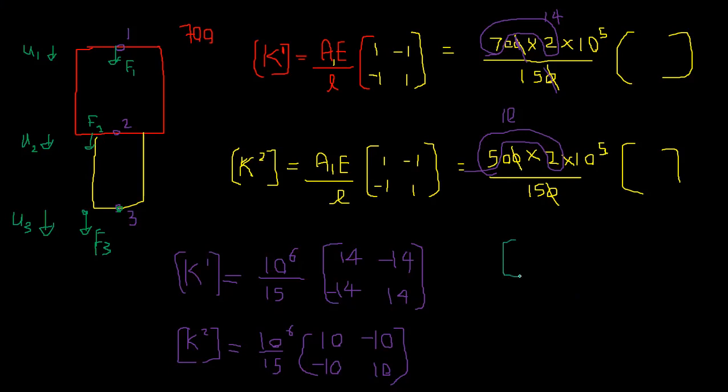So this is the simplest form. This tells you how the force and displacements are related. Actually these are u now, okay? F equals K u, where u is the displacement. So if you know this matrix, you can find these two. We have already found the K matrix, but for each element, and we are solving it globally. So we have to define the global matrix. This is how we define it, right?